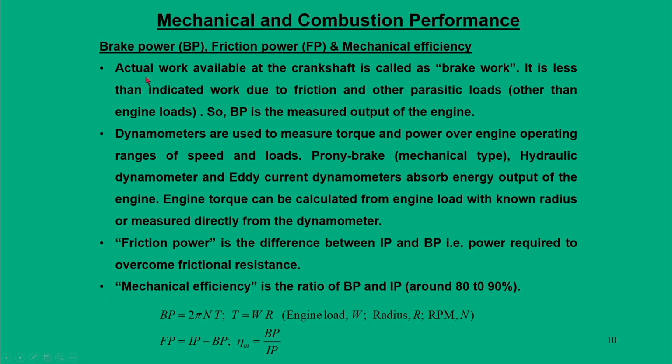So, just to explain this fact, I can say that the actual work available at the crankshaft, which we call brake work, is less than the indicated work. This is mainly due to friction and other parasitic load. Parasitic load means other than the engine loads.